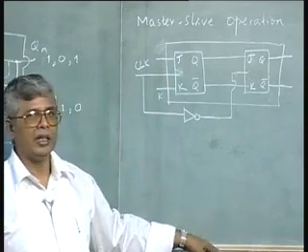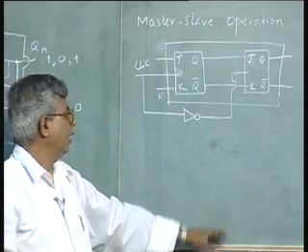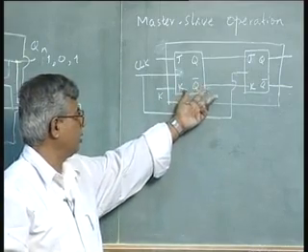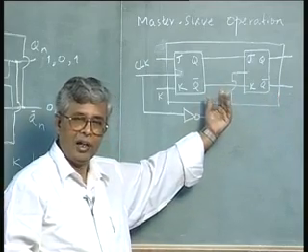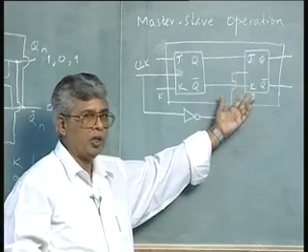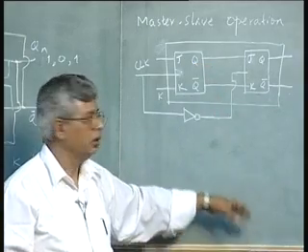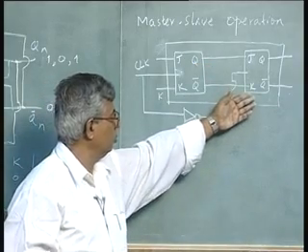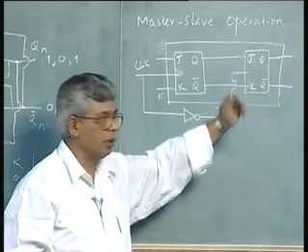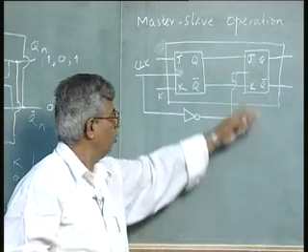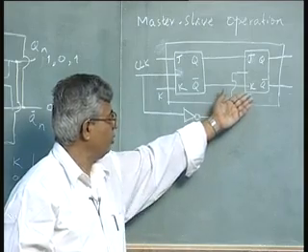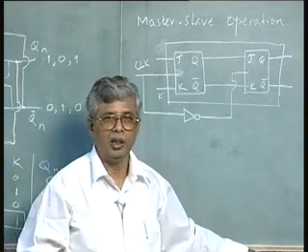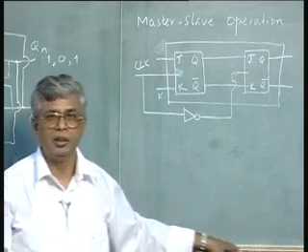So, when the delay of a gate is less than 1 nanosecond and there are a couple of gates in the path of this and a couple in the path of this, a total of about 4 or 5 gates, 4 or 5 nanoseconds corresponds to very high clock rates. 10 nanoseconds corresponds to 100 megahertz, 5 nanoseconds will correspond to 200 megahertz operation.